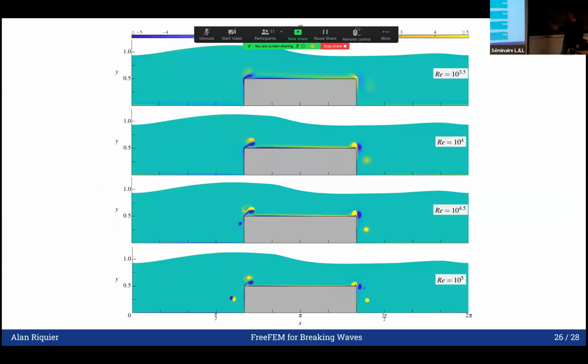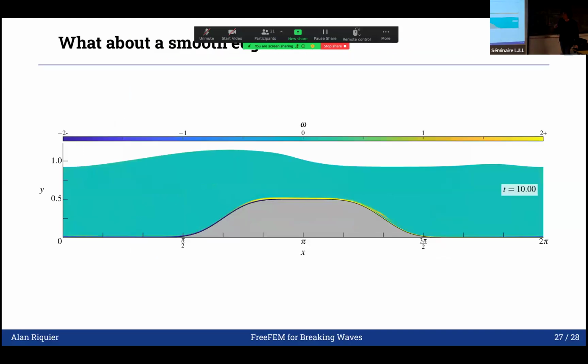What I can do is first show you the convergence as we increase the Reynolds number once more. So you see that it seems to converge to the Euler solution plus point vortices, but I don't know exactly when all these vortices are emitted. And I don't even know if the flow maybe becomes turbulent at some point. What I can do is smooth the edge using the well-known method of mollifiers from the analysis of PDEs.